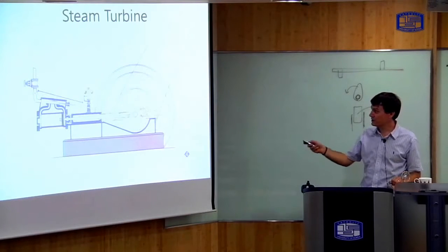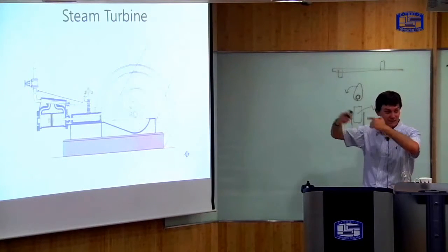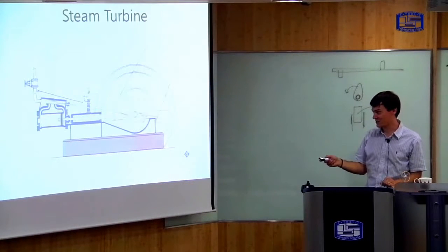The motion of the wheel itself controls the valves. Okay. So both the valve and the piston are connected to this wheel, about 90 degrees out of phase again. So that ensures that the piston is always being pushed in the right direction.